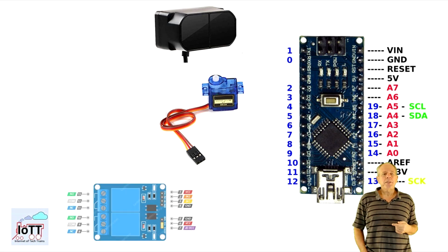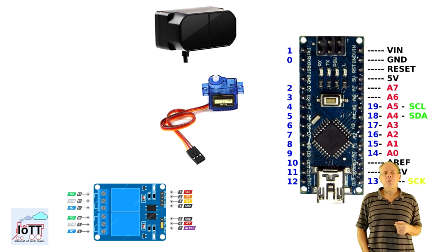A dual SPDT relay which allows for changing the polarity of the track. This could be done just in the software based on the input from the TF Mini. However, since I like open systems, I prefer to also send block detector information to LocoNet, so that I can have some LEDs somewhere else. And in the other direction, I'd like to connect the relay to a switch address, so that I can change the polarity from a handheld throttle.